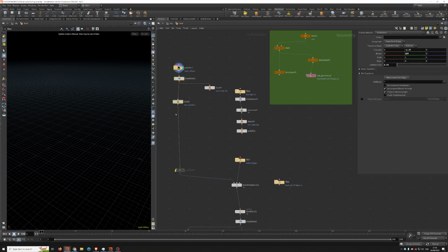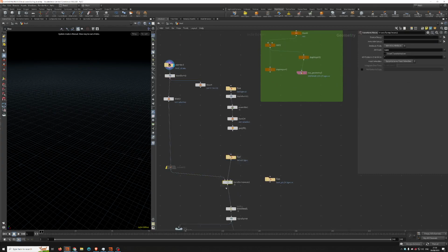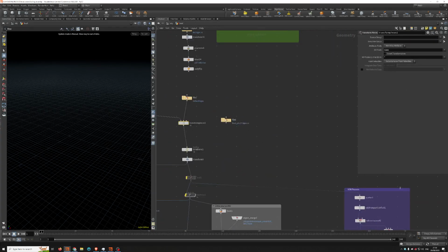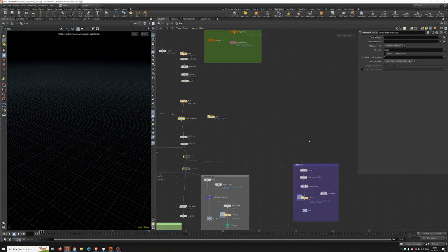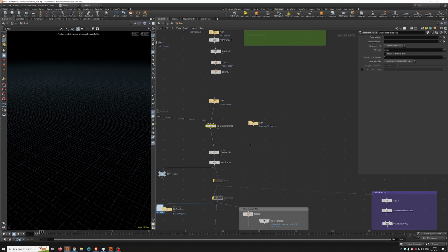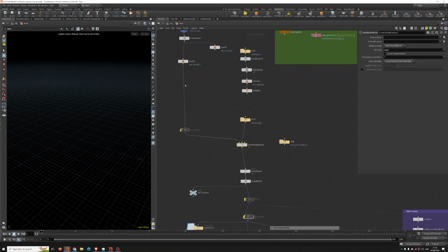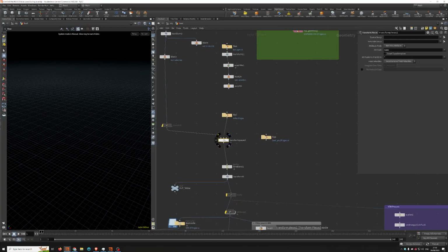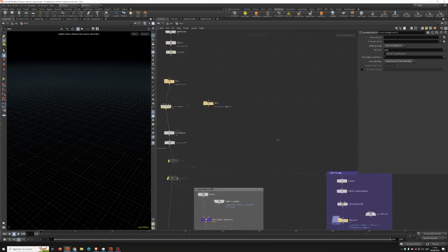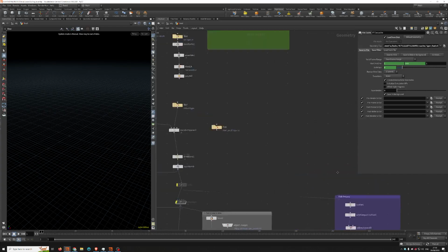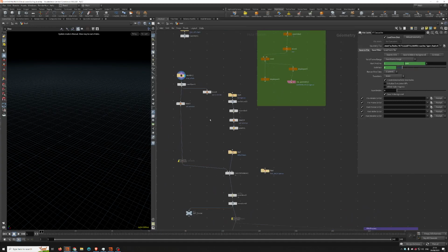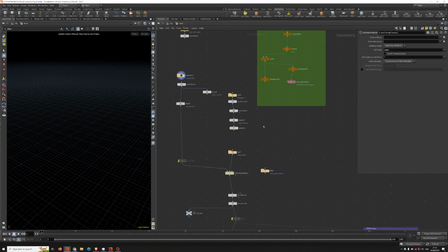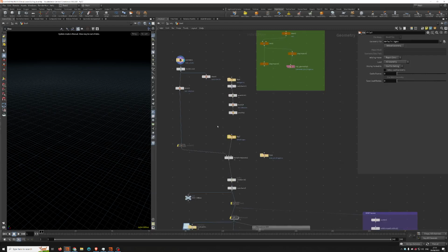In this case, for the boat, just bring in the file and use transform pieces with the match attribute name, and do the same for the VDB. Because it's moving, I did it this way, but it's a very old project. Normally we have to make a VDB inside, and then use the same transform pieces again to transform the VDB, so you don't have to write out a big file as I did here. You just write one VDB one time, and transform pieces with the same animation, with the same points that you simulated with the flip.